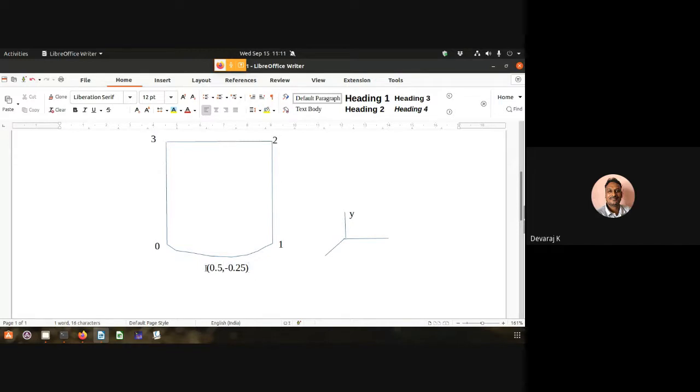So how are you going to define the arc? It can be defined where I want it, between 0 and 1 and the dimension. This I can do in your blockMeshDict file. If I do it for both the surfaces, I'll get the curved surface.